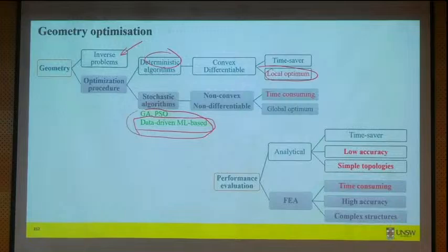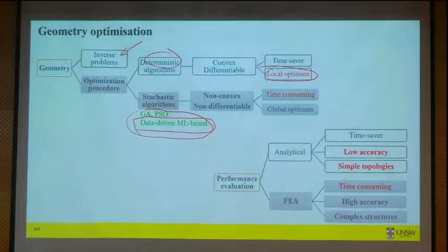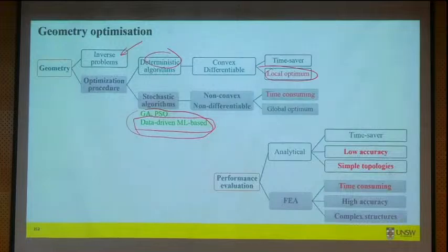Because many of the designs may satisfy our objectives, you have to sort out those designs. But to sort them out, you need to evaluate the performance of each design that you are getting. To evaluate, you could use an analytical model, or we could use finite element. An analytical model is usually quite quick, but as we know, it doesn't consider saturation and leakage, so accuracy could be low, but it's simple.